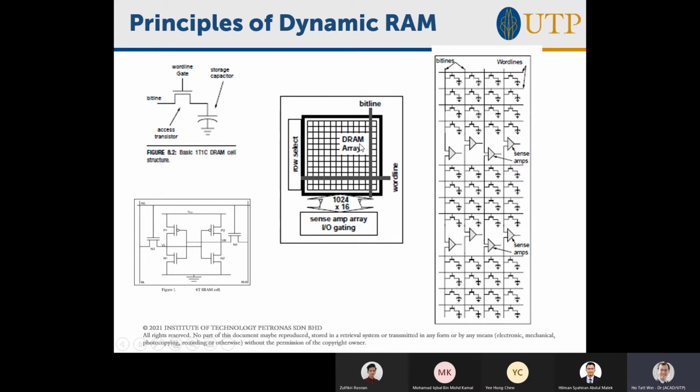Okay, and the way RAM is organized is in a grid fashion like this, right? So this is 1 bit, this is 1 bit, this is 1 bit, this is 1 bit. And this is called the bit line, because the bit is going to be read out here. Depending on which bit you select, it will be read out here. And how do you select which bit?